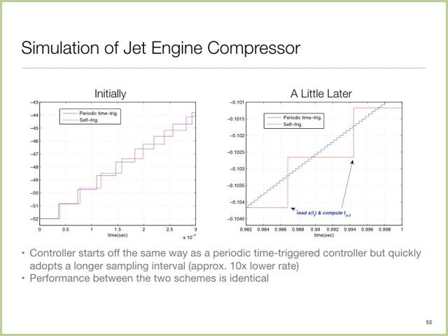Now, I guess the philosophical question you can ask is the following: if I have a model of the plant, why do we do controls? Why don't we go open loop? If I have a model of whatever I'm trying to control, then why do I need a control system? Uncertainties, right? Not just modeling uncertainty, but also noise and perturbations and stuff like that. So that's why we do feedback control.